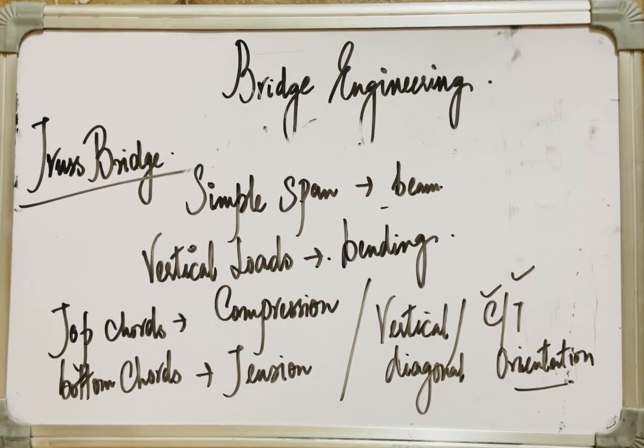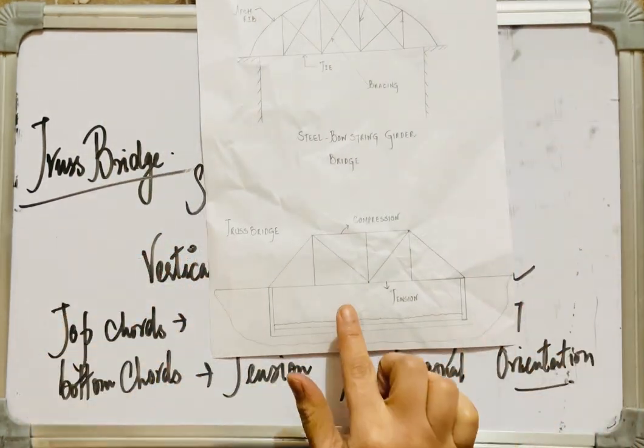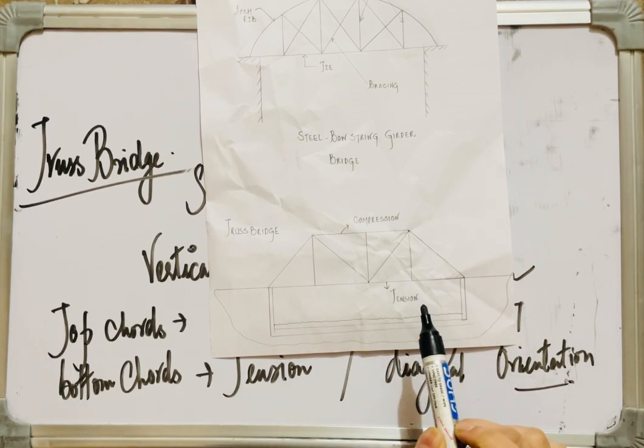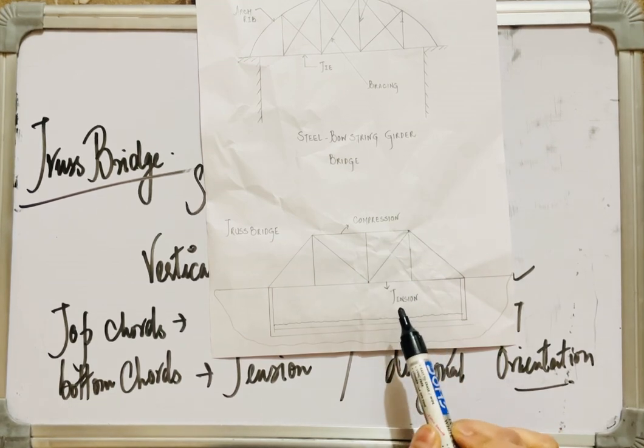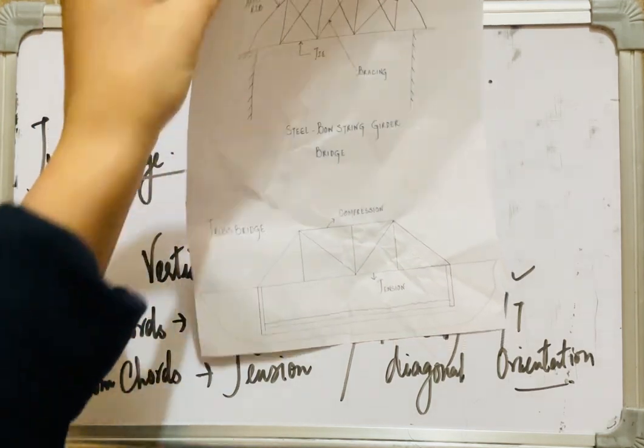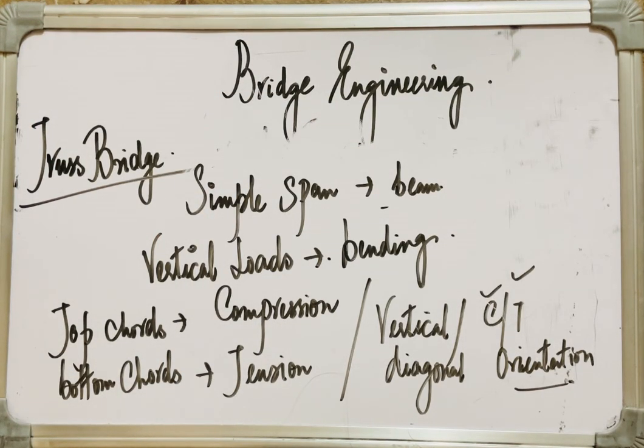All right, so here in the diagram you can see a truss bridge wherein we have incorporated the triangular units, the steel trusses, to support the bridge deck. The top chords are in compression, the bottom chords of a truss are in tension, and the vertical or diagonal members can be either in tension or compression. That depends upon their orientation, and that's why, as we discussed earlier, these truss bridges are capable of handling dynamic loads and can absorb both tension and compression. That is why they are renowned for this sturdy framework, and this geometry provides them exceptional strength.